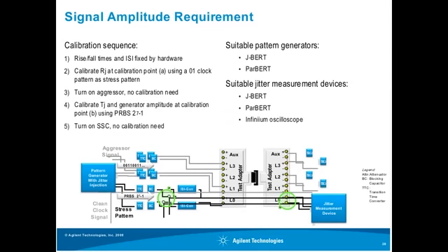I mentioned several times that we need to calibrate sinusoidal jitter, and we need to calibrate the amplitude. The way this is done is we have a pattern generator with some accessories, which are basically the transition time converters and the ISI, and we run the signal into a test adapter, and then we plug in another test adapter. So if this is a plug, this is a receptacle.